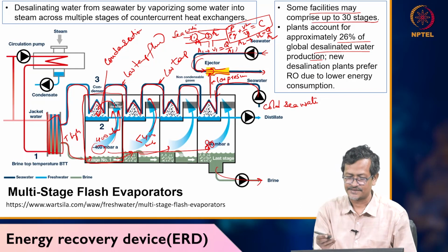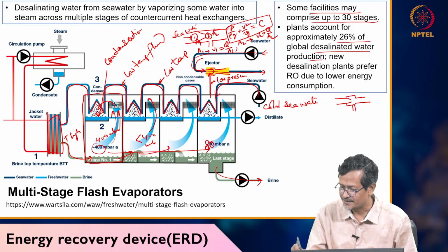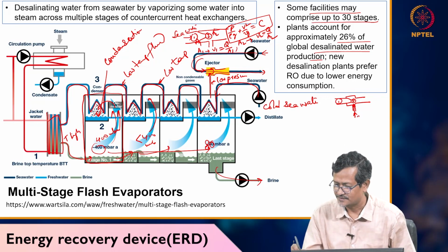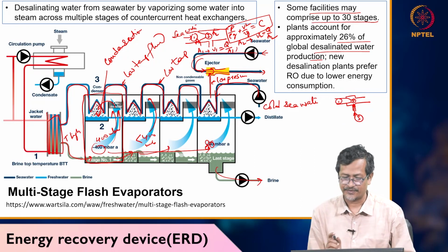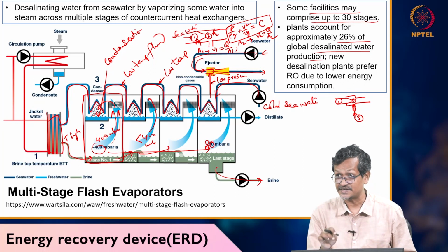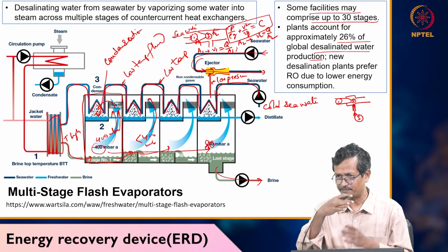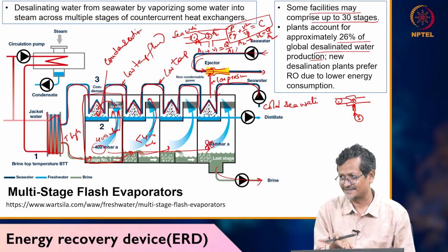So, the system is like this: I have a pipe, then the size is reduced, then the design is like this, okay. There will be an intake pipe. So, 1, 2, at point 2 your pressure is reduced. So, point 2 is connected to this one, 3, okay. From 3 fluid will be sucked, or it will create low pressure, okay. Whatever low pressure you are creating is because of this ejector effect, okay. You have one pump pumping high pressure fluid through a nozzle, the nozzle creates low pressure, and that low pressure is connected to your stages, okay.